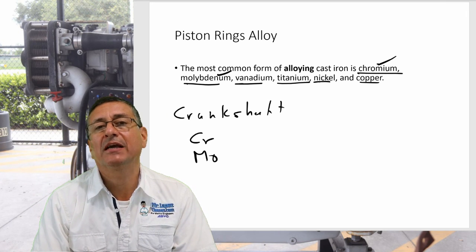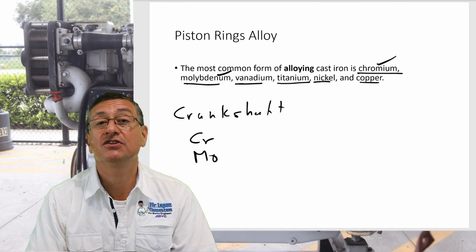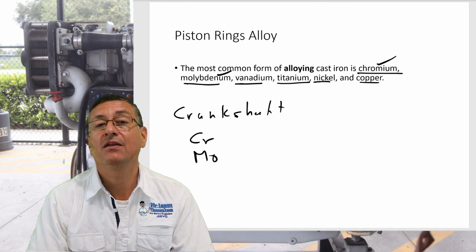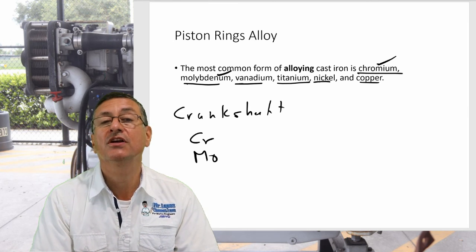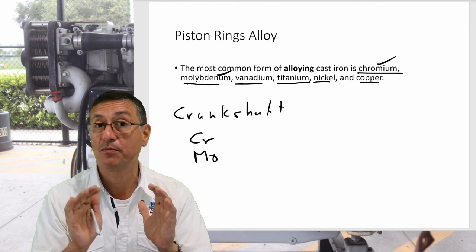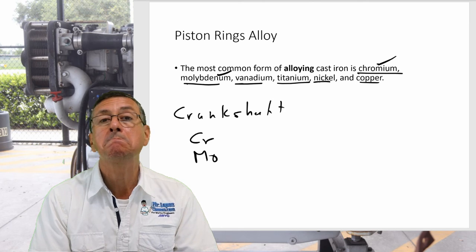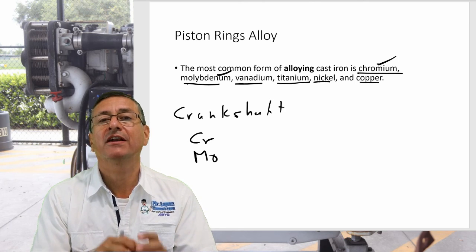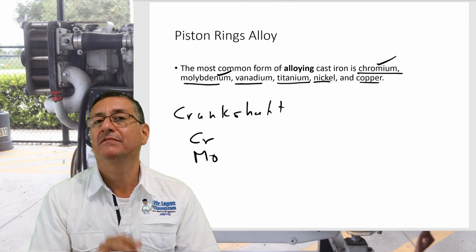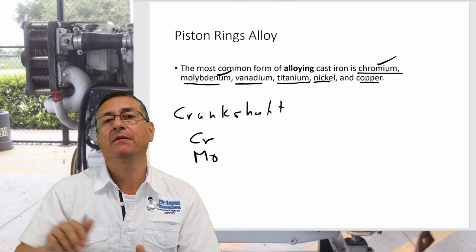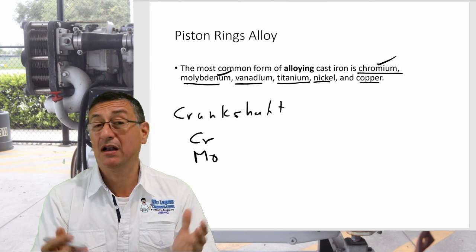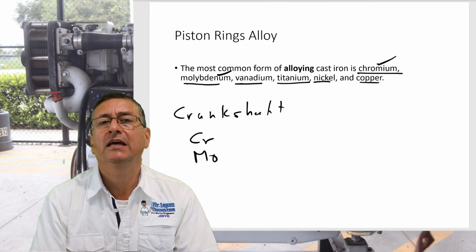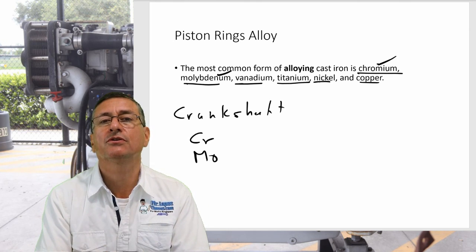Yeah, this is the typical consequence, because the compression is not enough, and when the fuel is injected at the end of the compression, the pressure is not enough and the temperature is not enough, and the fuel never ignites, and the fuel goes out through the exhaust pipe. This is the typical consequence of low compression, and of course you have misfiring. The engine is not running softly. You have vibration on the engine.